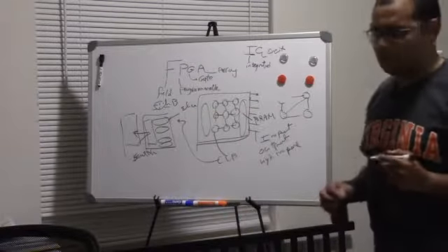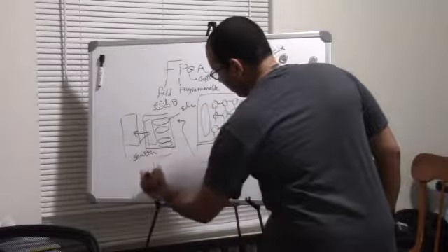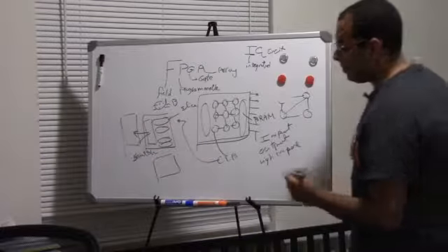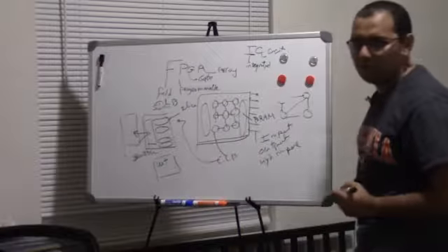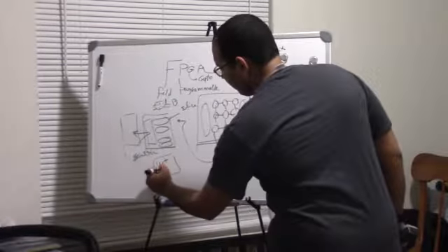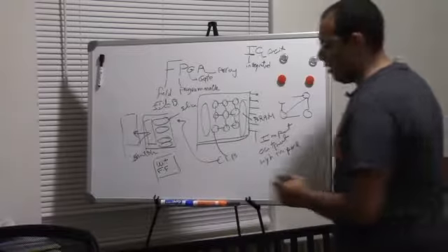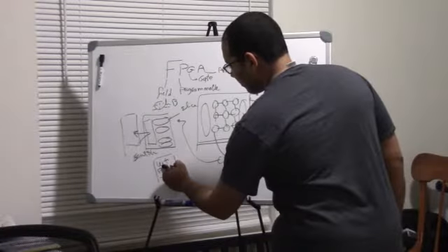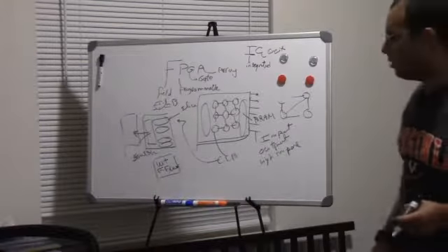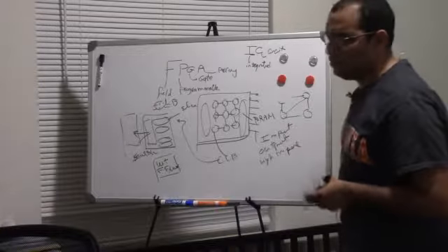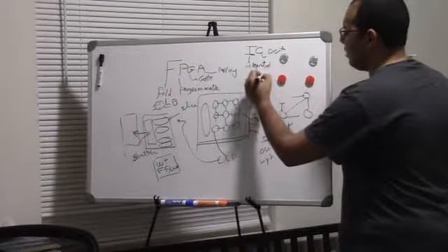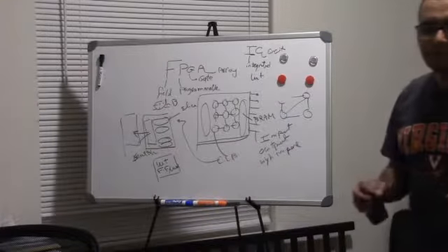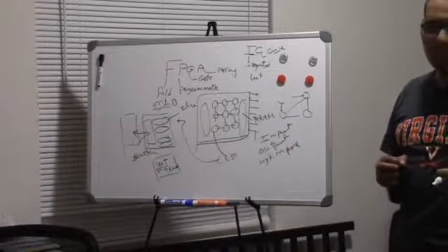Inside the slice you will find a couple of lookup tables, LUTs, flip-flops, and muxes. What are those for? Okay, what do we mean by those things, right? So the LUT, lookup table, can be used for storing data.